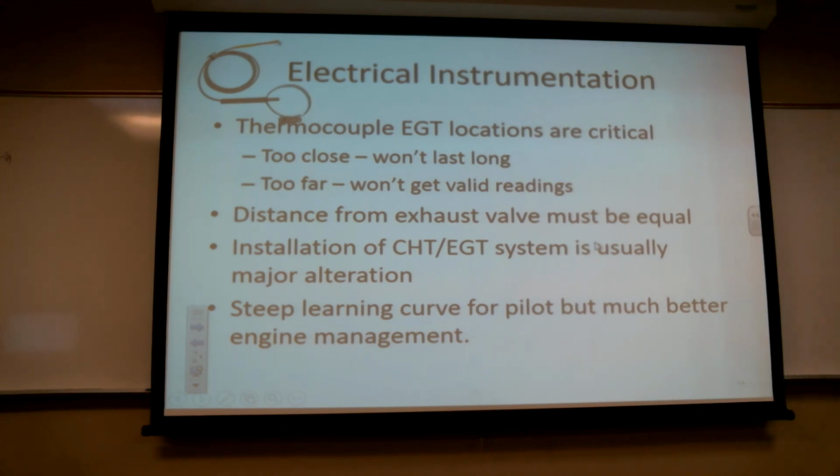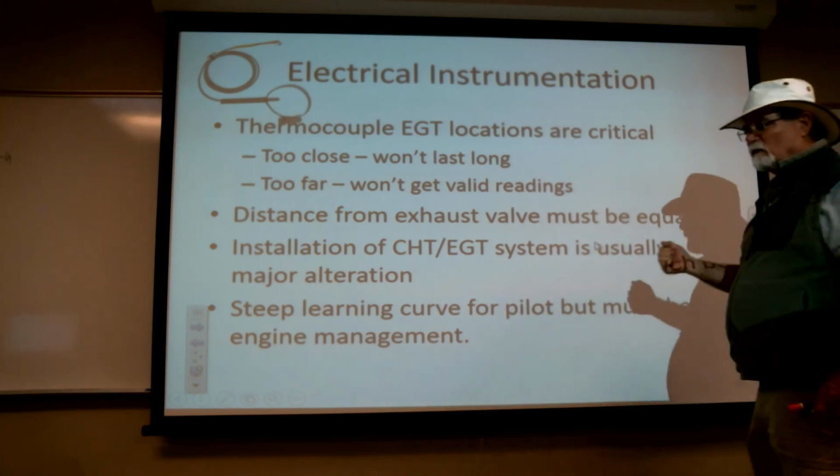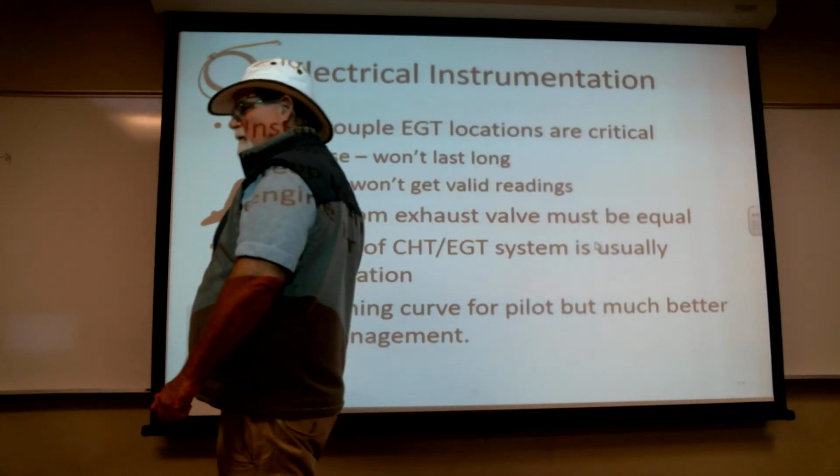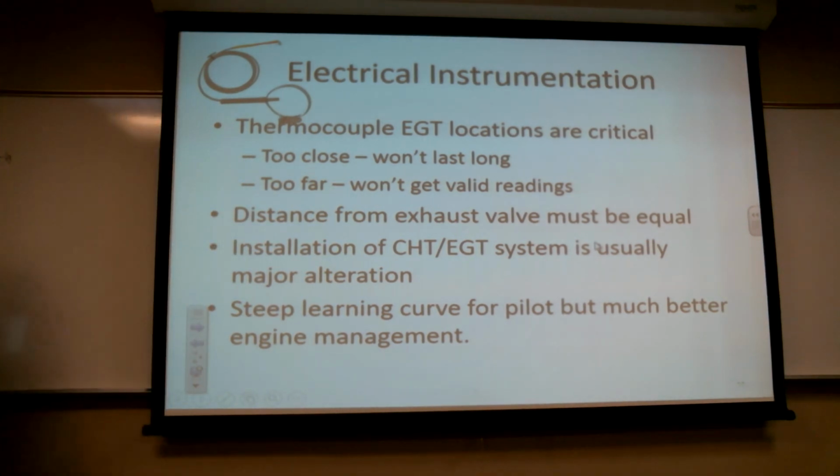And if it's fuel injected, they'll all do it pretty close to the same value, same place. That's where I want to run the engine if I'm below 75% power. So if I'm cruising. At any value above 75% power, it's not going to matter because I'm going to want to be at full rich because that's what the manufacturer says I must do. And if I'm operating at higher power, I have to do it. If I just want to keep my warranty valid, I ought to do it.